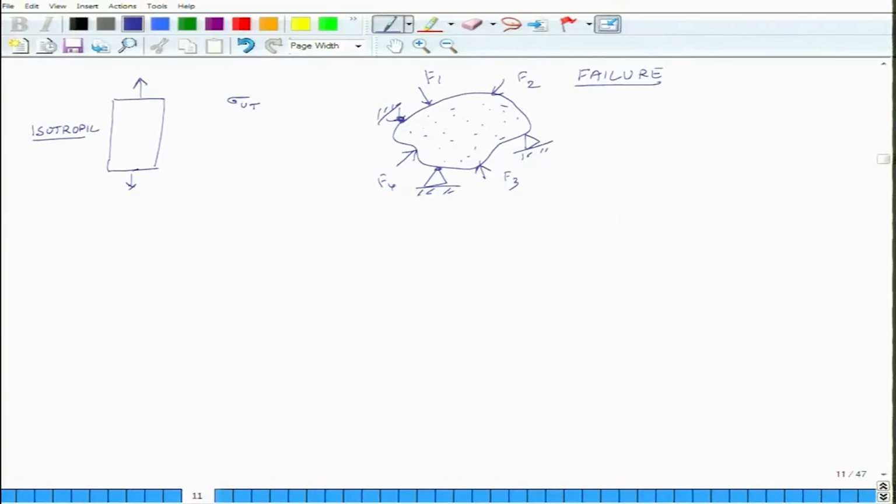But essentially, the point is that at every point in the system, you figure out what the stress is, and then at all these points, you find out what the principal stresses are, right. You want to know whether this structure is going to fail or not, and then you use criteria like principal stress criteria, principal strain criteria, von Mises stress criteria, distortion energy criteria.